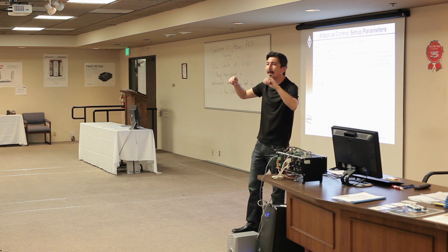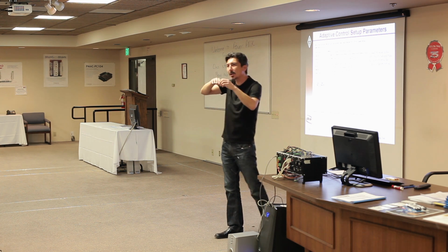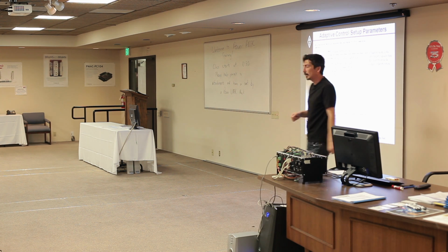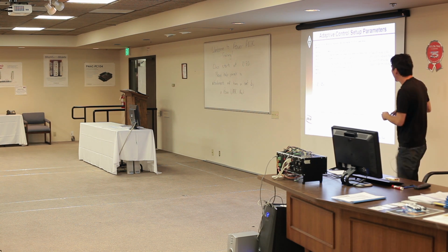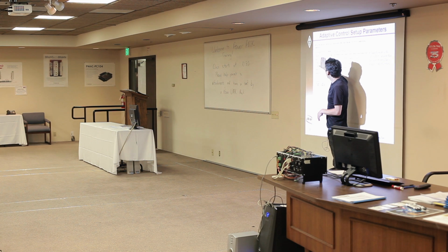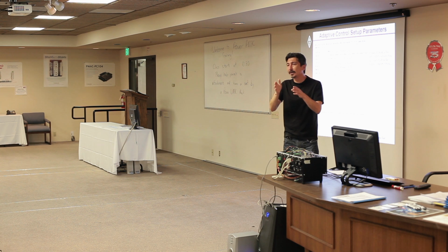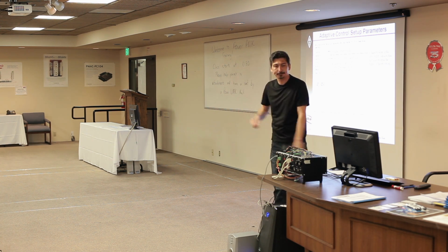That's why we call it gain. It's not gain scheduled adaptive control in some sense, because it basically changes linearly with respect to your estimated gain. And it also has a setup page similar to this, but instead of nominal gain, you basically ask for minimum gain and maximum gain, and it asks for the desired bandwidth and the damping ratios for those endpoints.